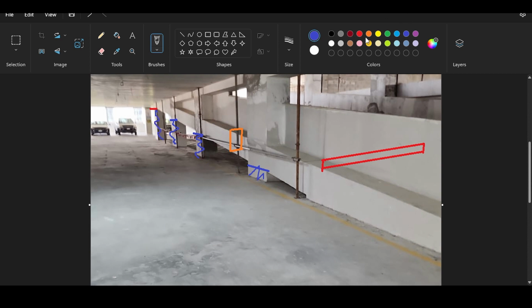Stage two is to do the formwork and cast your beams. Now notice, a lot of times you would have a pre-stressed beam or even pre-cast, but we are not going to do this because in this video series I'm trying to have simple reinforced concrete. I am thinking of making a pre-cast series later. I don't think Robot has the ability. I need to research that, but I have some software I can mention. Anyway, you cast your beam as well as your slab of the ramp. And then in stage three, you could continue the casting of the rest of the column.